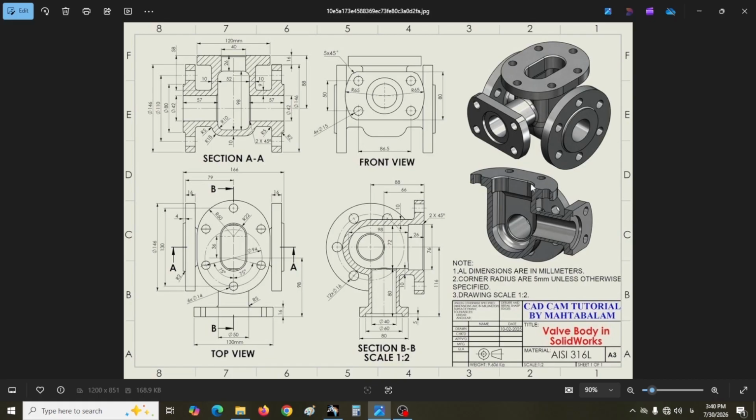The first part that I will draw is this vertical body. Look, I can use the top view and draw it in a sketch. Then I can extrude the sketch downward with the pad tool. First, I will do this.